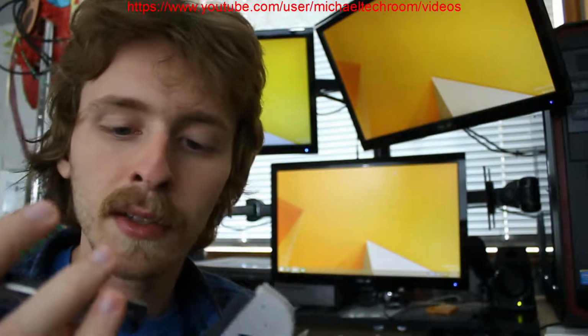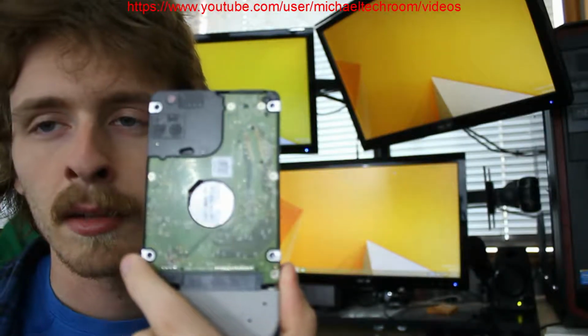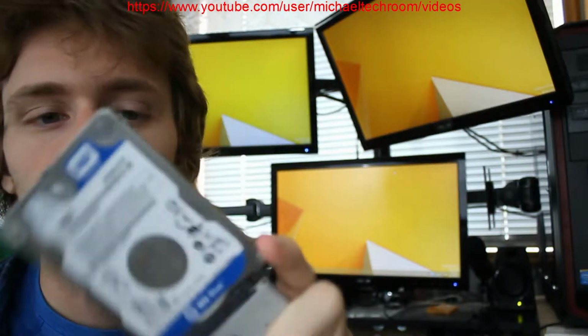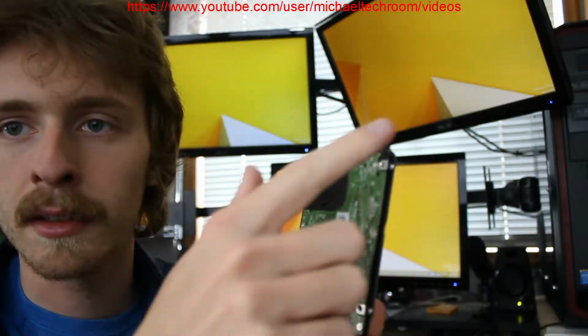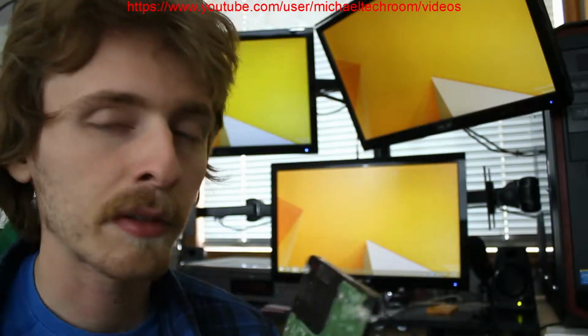So all you have to do is detach it. And now another bad point with these mechanical hard drives is the circuitry at the back, that's mostly exposed, so just be careful how you set it down, I guess. Unless you have feet to keep it up, but just be careful. With an SSD, you don't have to worry about shorting something out, so that's great with SSD. But with a mechanical laptop drive, you do have to be a little more careful. So wood or paper would do just fine to separate it.